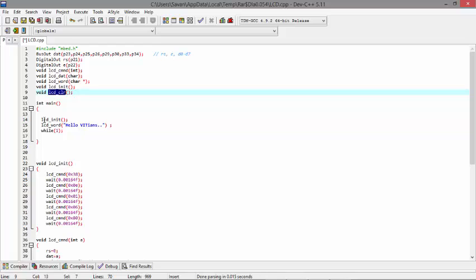Inside the main, I just call LCD init, that is LCD initializing. For initializing the LCD, I have to write a few commands that I explained here. First command is 38, we've already seen the function of all these. Set the first line, then 0E, then 01. 01 is for clearing the display, so no garbage will come in your display.